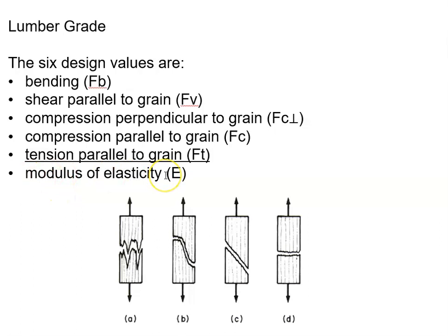And the modulus of elasticity, I couldn't really find a picture that expressed that very clearly, but we know that is a measure of its stiffness, of course, and that is found on the stress-strain curve in the elastic region. So that is a measure of kind of the deflection as we walk the floor, and the joists are kind of bouncing a little bit. That is the stiffness, and of course some bouncing, a little bit of deflection is allowed.